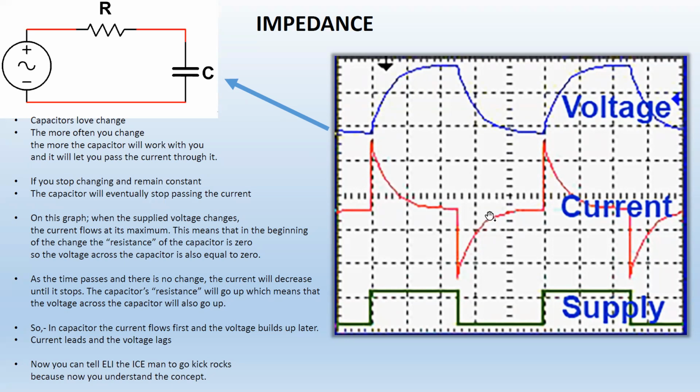Then it shoots down, because the charges accumulated there are still there and have to go somewhere. So you're going to have a negative inrush of current with double the size, from here to here. Again you get an inrush of current the other way, and the voltage behaves just as it does here.